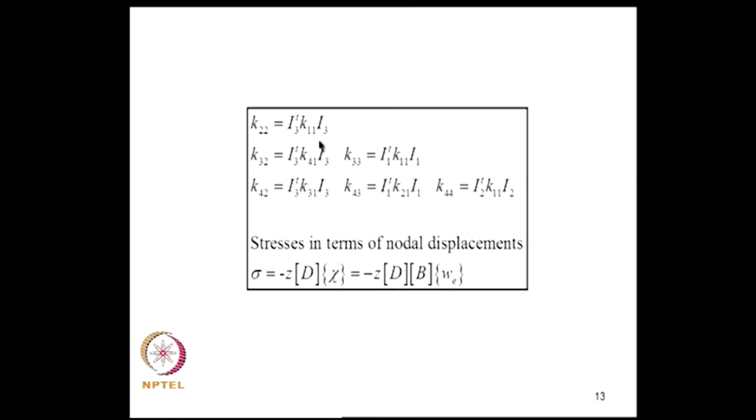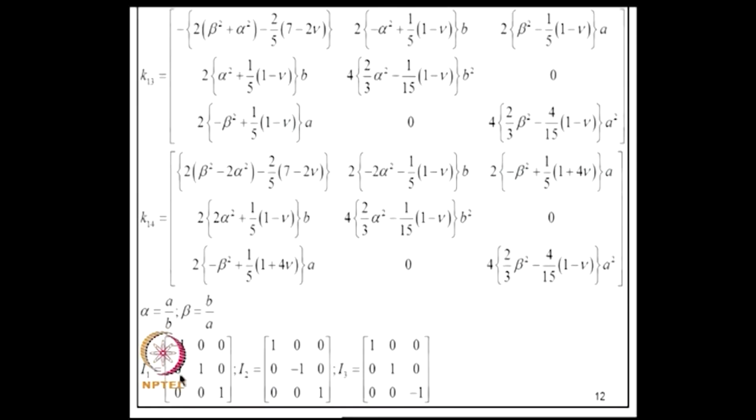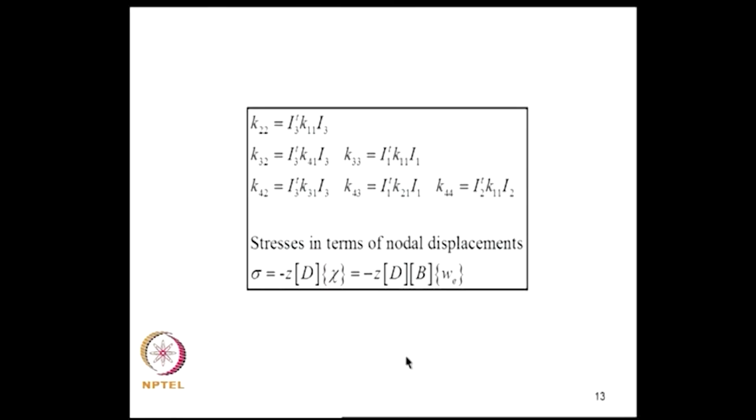1 1, 2 1, 3 1, 4 1 matrices through these matrices I 1, I 2, I 3, and these details can be worked out. I leave it as an exercise for you to carry out these evaluations. Once the stiffness matrix is determined, it is determined exactly in this case. The stresses in terms of nodal displacements can be evaluated by multiplying the strain vector with the D matrix, and we get this.